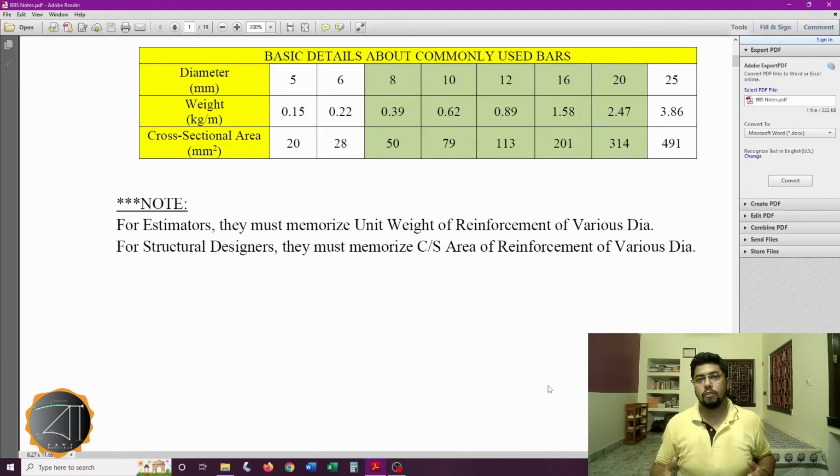In short, while thinking as a structural engineer, we are not much concerned with how much weight of reinforcement we are providing in a particular part of the structural member. We are only concerned about the cross-sectional area for the particular critical structural phenomenon, like whether we are calculating the reinforcement for taking up the flexural tension, the diagonal shear, that is the diagonal tension, or the compression.